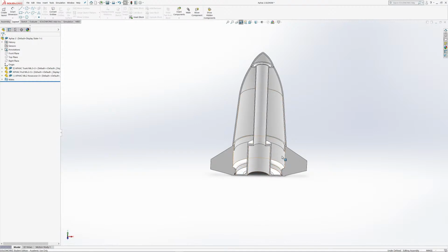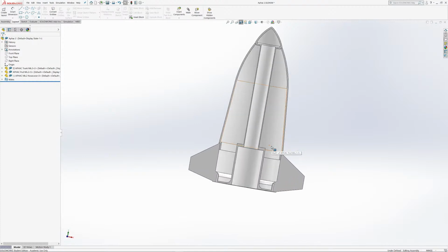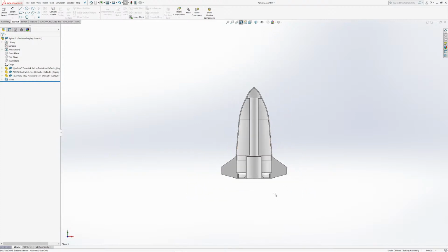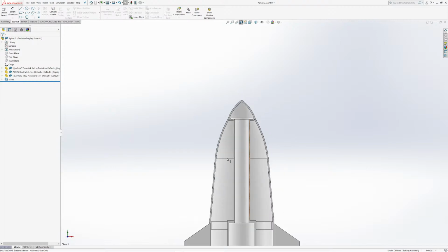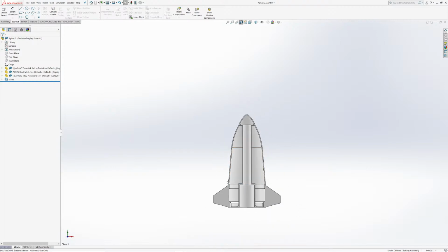One is to put the batteries down here in the trunk segment, because the engine is relatively long compared to this. It's going to go down to about here. So we think to counter that, we can put the batteries here, and that should stabilize it a good chunk. If that doesn't work in the simulations, we can also put them up here in the upper part, which adds the weight in the nose cone, which should counteract the pendulum effect.